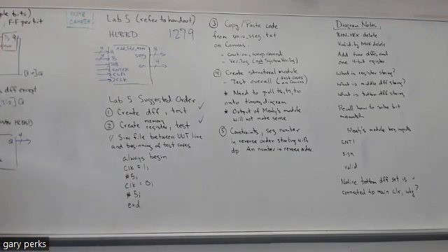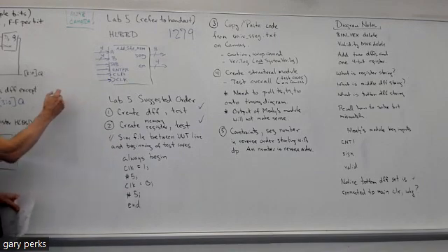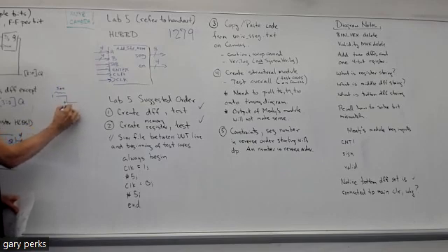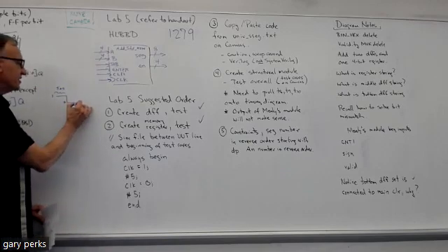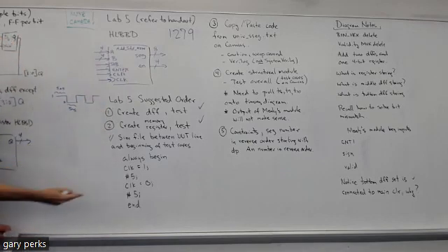Well, here what we're doing in this always block is that we have this clock that we're setting to 1, and then we're going to leave it 1 for 5 nanoseconds. Then it's going to go to 0 for 5 nanoseconds. And then anything within an always block just runs forever. It just runs for infinity. Okay, so this is just going to keep going along. Okay, so this code will generate on your timing diagram this periodic square wave,